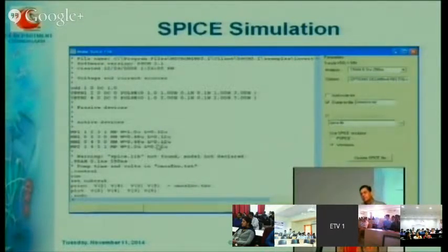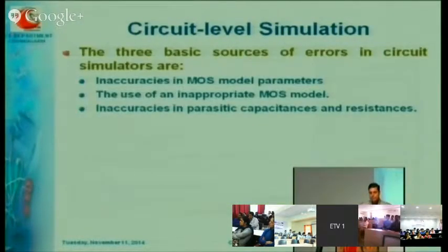So basically whenever we shift from schematic to Verilog file, it is nothing but your SPICE file, or sometimes we also call it a netlist file, and that file gives you information about each and every device present in your circuit with its actual physical description. So this is the SPICE file, and we use this SPICE file and compile it to get the layout.